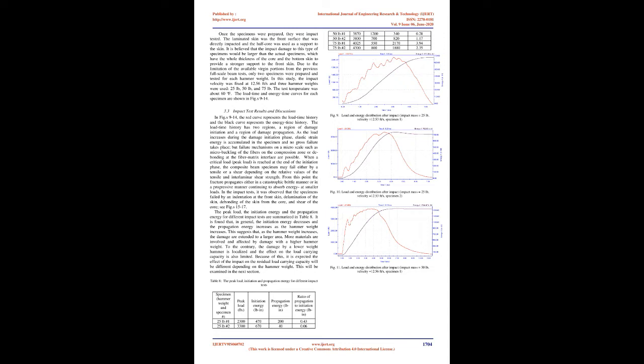In order to validate if the Euler beam theory was applicable or not, a theoretical analysis was conducted to compare with the experimental results. From flexural bending of a Euler beam 13, we have the following relation between the strain and bending moment. 3. Where ε equals normal strain at a point with a distance y from the neutral axis, M equals bending moment, lbf-in, EI equals bending stiffness, lbf-in², y equals distance from neutral axis to desired point.